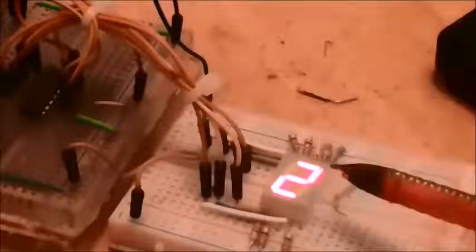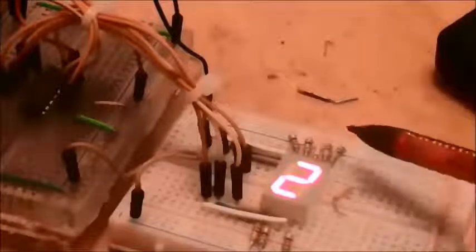Now when we looked at 7-segment LEDs, we looked at what was the common cathode. So you lit up through all separate anodes, and you took out through one common cathode to ground. And that's the most easy way round to do it. But here we're using common anode. So what you do is you put power in at the anode, and doing that, all of the segments will light up, providing they've got a resistor at the cathodes.